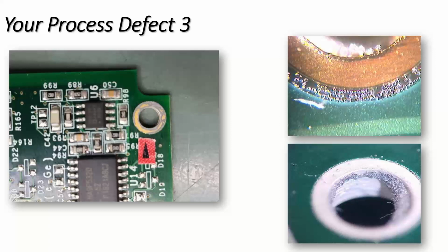And the second example on the bottom is solder paste which is in the through hole or the fixturing hole, and the actual volume of paste in the hole or around the hole, around the resist and the pad on the top image, is way more than would be required to give the contamination you see in the photograph.